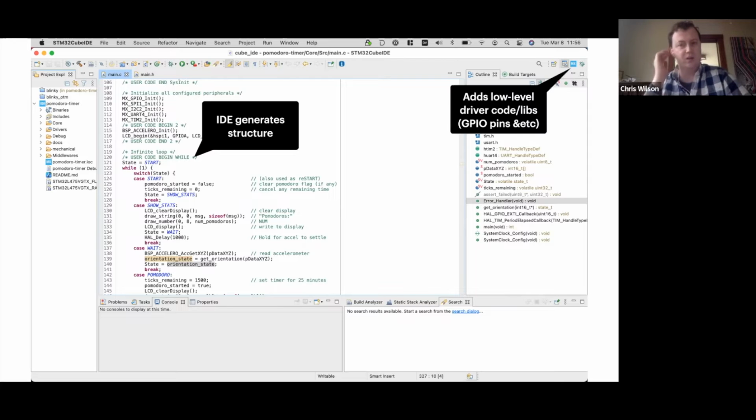It had a little configurator tool where you could say, okay, I want this pin to do this function, and please turn on USB, that kind of stuff. It would generate the code and dump it into the project for you. Then all you had to do was include the headers and things like that. So it made getting up and running easier.